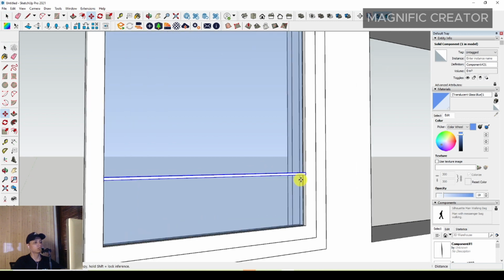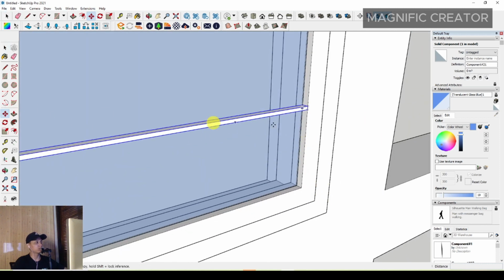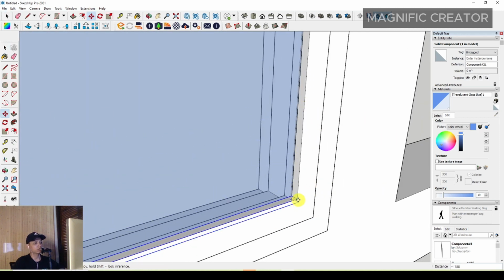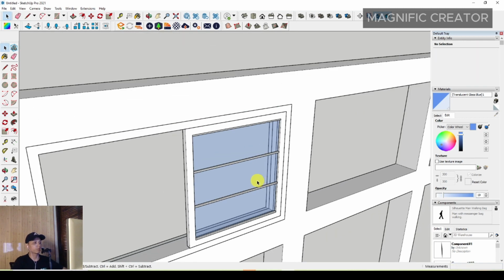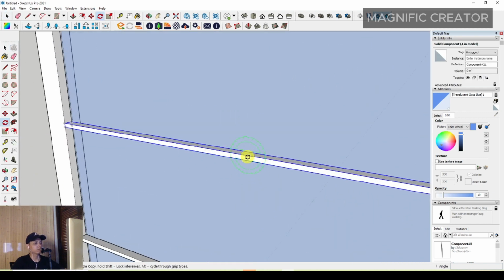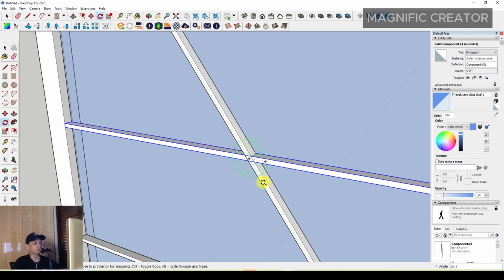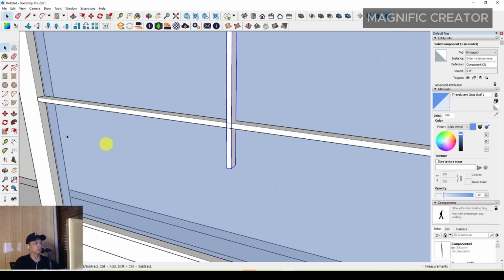You can position it, or move it to the bottom first, and then press Control and position it in this position, and type 3 slice and press enter. After that you can rotate it with the rotate tool, press Control to duplicate, then type 90 degrees, and then move it.